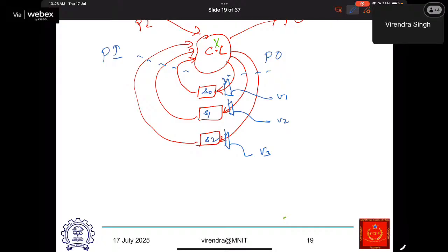So if I can have these 3 multiplexers and 6 additional primary inputs, in that case, I can write anything at any point in time in these, say, flip-flops. So if my combinational ATPG needs 0 from here, 1 from here, and 0 from here, in that case, I can always assign 0 here, 1 here, 0 here by assigning 0, 1, 0 here. This needs 6 additional primary inputs.